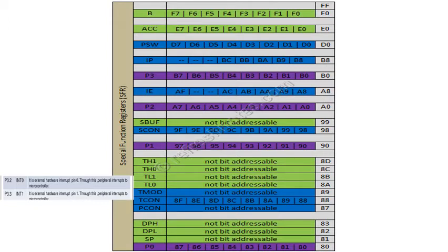IE0 and IE1 are used to tackle the problem of looping inside the interrupt, which occurs during an external edge-triggered interrupt. The CPU sets IE1 and IE0 to 1 when it encounters an edge-triggered signal at either of the two ports. When this bit is 1, the CPU ignores any other falling edge signals on the port, preventing the interrupt from reoccurring.